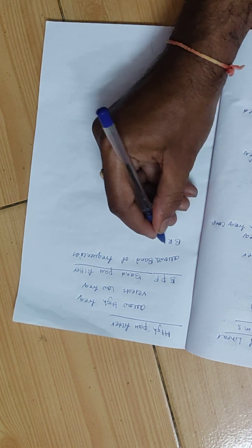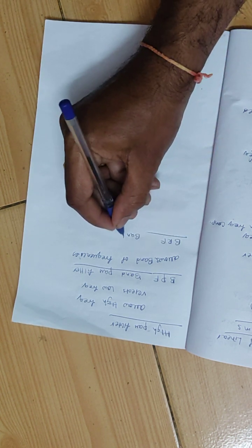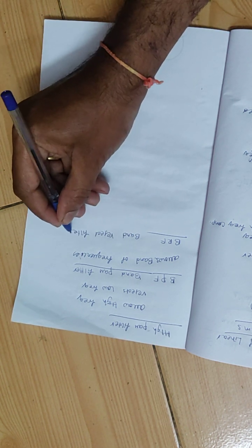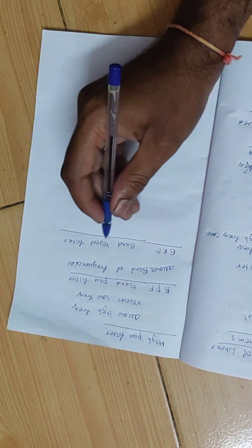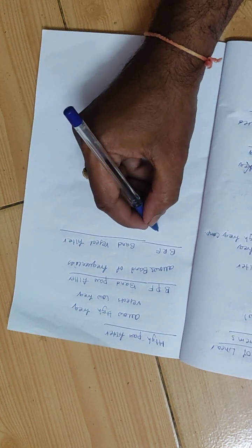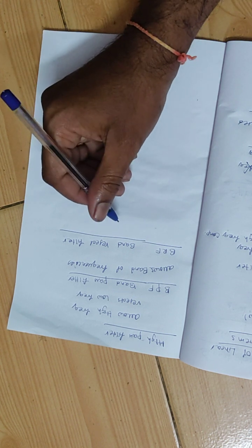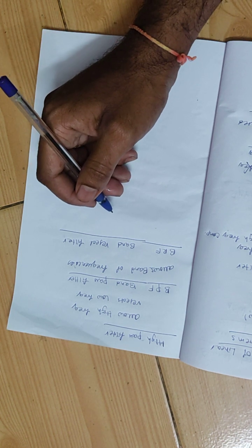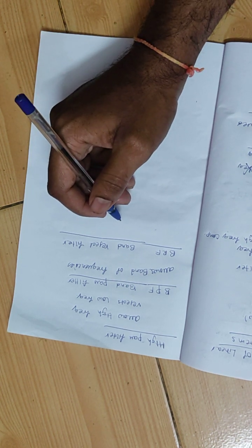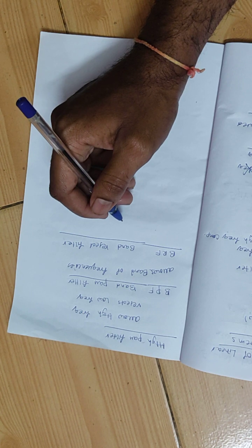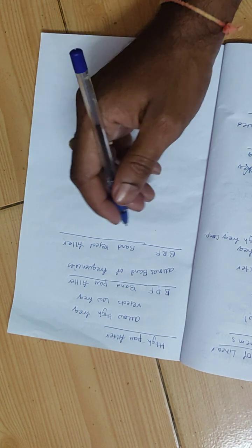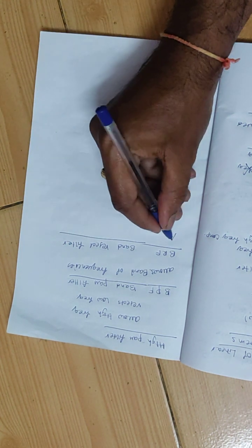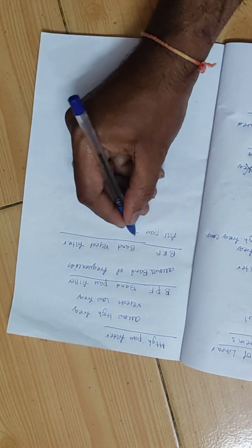Next, band reject filter. I'll show all these filters' frequency responses. Band reject filter means only a band of frequencies will get rejected and all other frequencies will be allowed. Coming to the all pass filter, all the frequencies will be allowed freely. And then what is the need for the all pass filter?